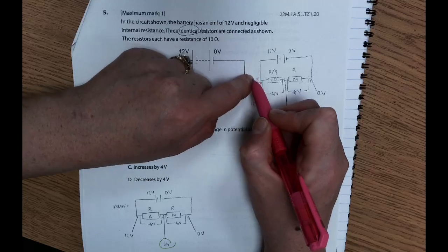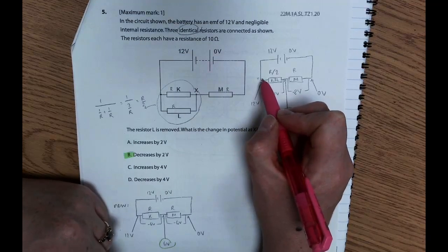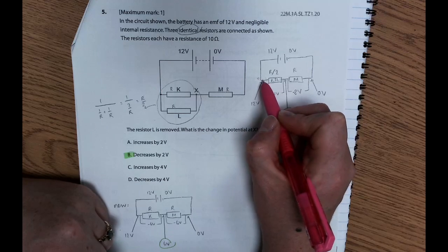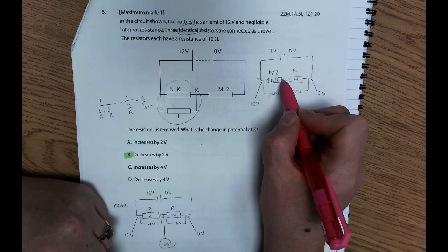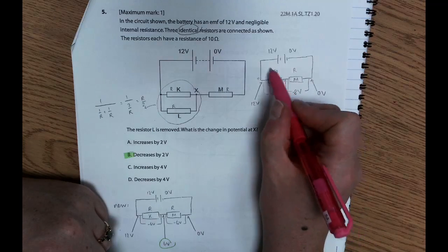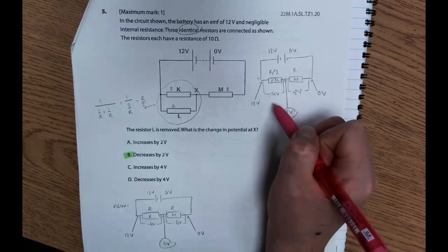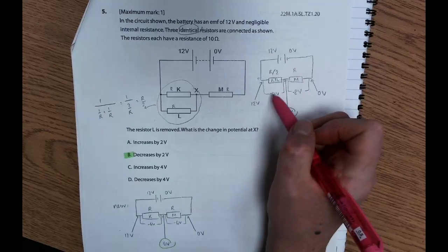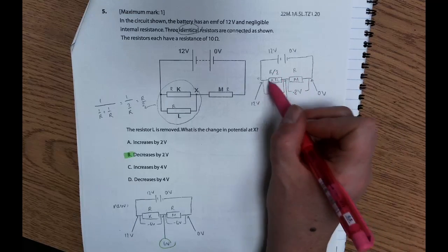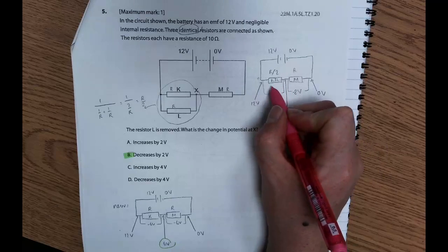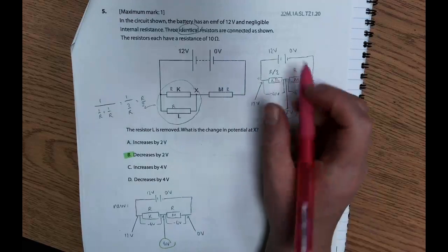Okay. At this point in the circuit, nothing has happened yet, so the charge still has a potential of 12 volts. Once it travels through K or L, its effective resistance that it's travelled through is R over 2. It has taken half the amount of the voltage that M will take. Okay, so this will take 4 volts when this will take 8 because this section is doubly difficult than this one. So as a charge moves through either K or L, they will drop 4 volts in potential.